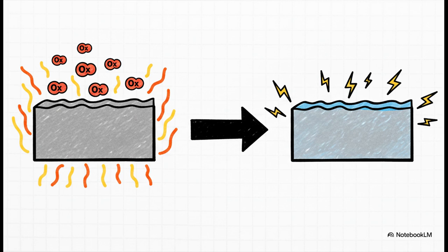Okay, next up, we have to prep that canvas with a protective coating. We use a process called oxidation to grow this incredibly thin, flawless layer of silicon dioxide, which is basically just ultra-pure glass, right on top of the wafer. This layer is absolutely crucial. It acts as an insulator, making sure the electrical grid we're about to build doesn't short circuit.